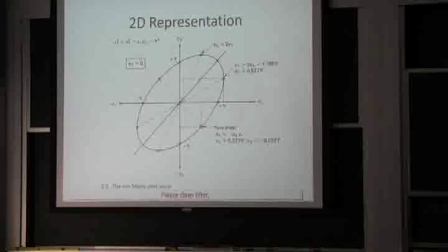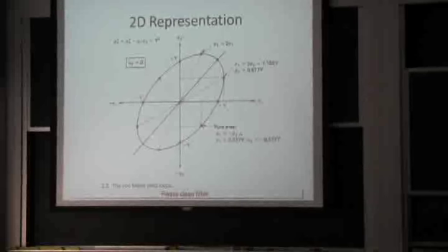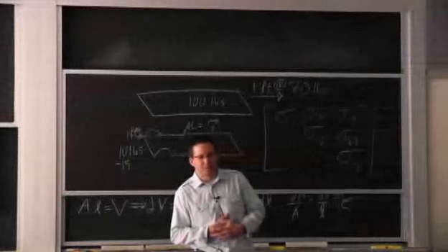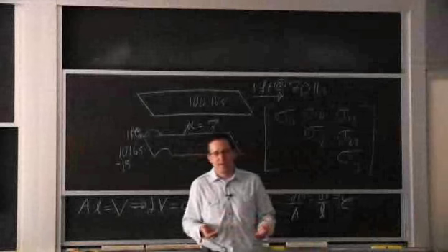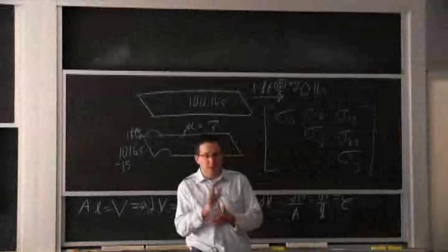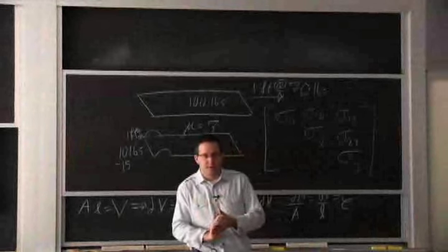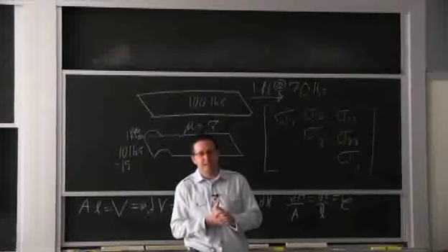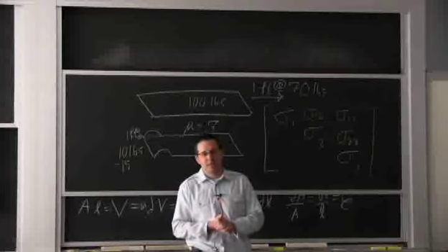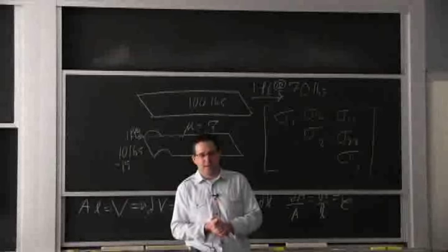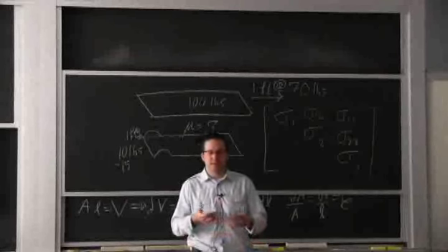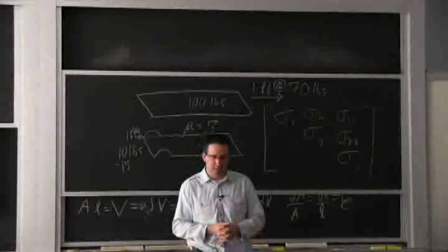Well, the wrap-up is to keep in mind the stress-strain curve. The reason I derived it, we talked about it, is it doesn't have anything to do with really the fracture. It's just a tool. Definitely it gives you the initial yield, right? So you can put that into the von Mises, it gives you some idea, it gives you the hardening exponent, which you can also use. But that's about what we get out of a stress-strain curve that's very scientific in detail. After that, the fracture depends on your specimen geometry, and we talked about that.